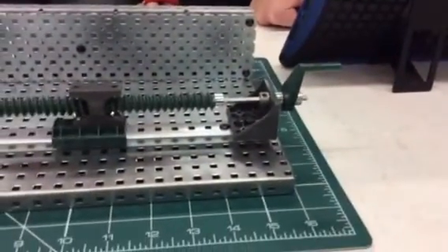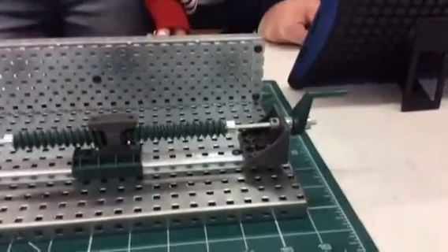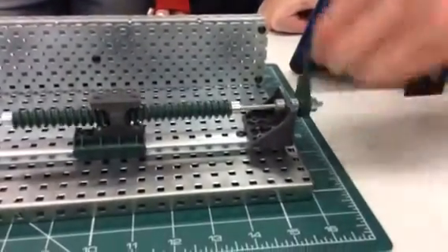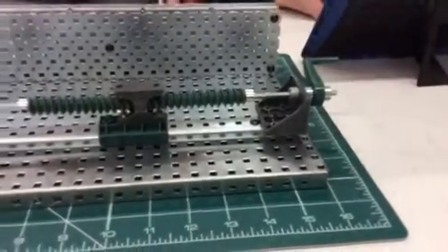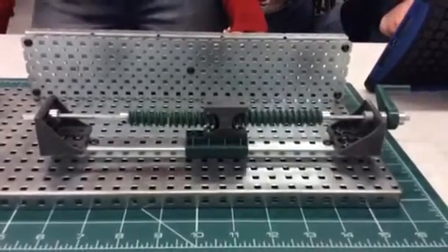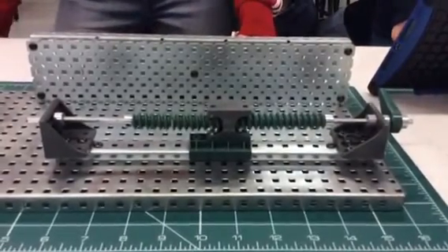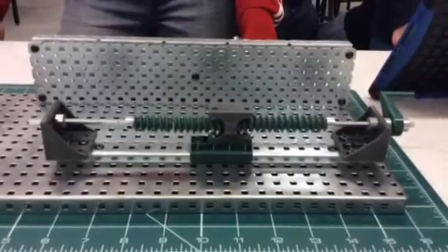And this is our mechanism, lead screw. Our lead screw's input movement is rotary, and the output movement is linear. The direction is reversible, and the flow of power is not reversible. They're typically used to carry high power, but not for intermittent use in low power actuator or positioner mechanisms.